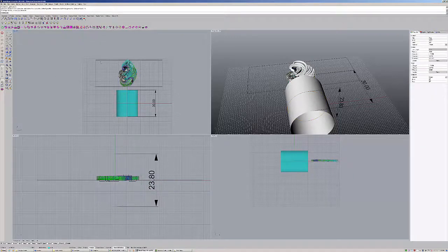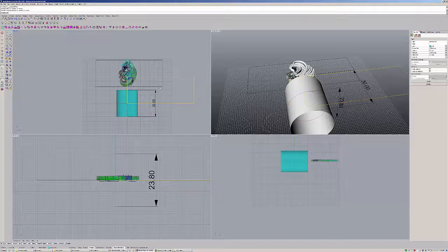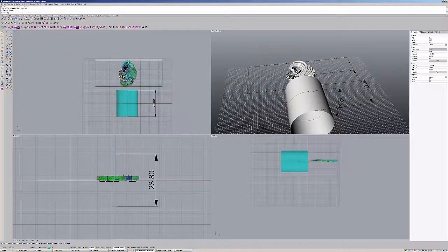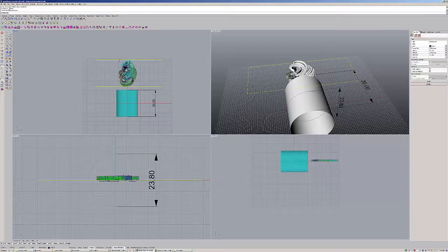Then we go to the left-hand side, and under the project curves, we click and hold, and click on create UV curves with the left click. Then we choose the object with another left click, and right click, and that creates the UV curves that you're going to draw in. Since we have it already drawn, I'm just going to show you by highlighting it.